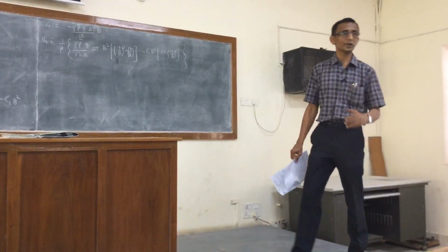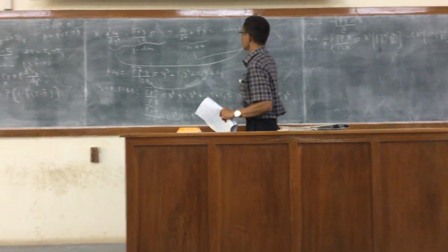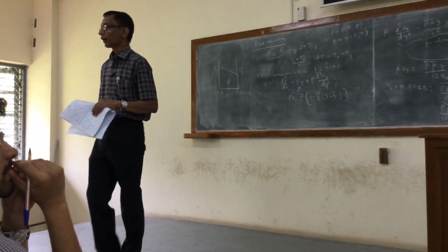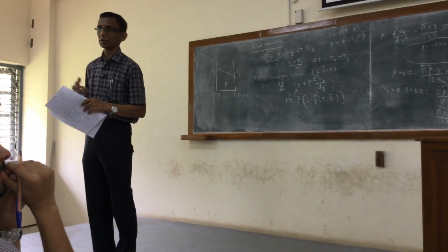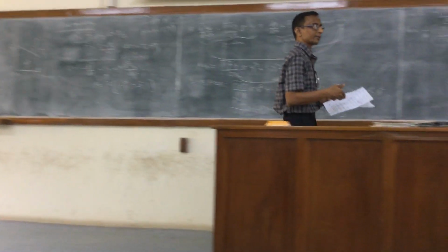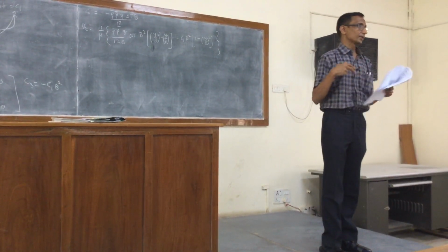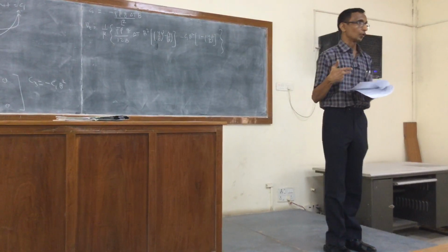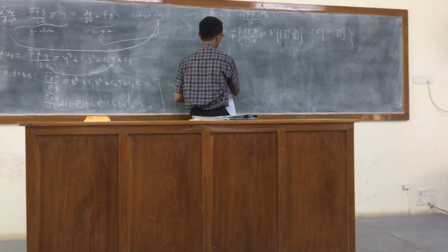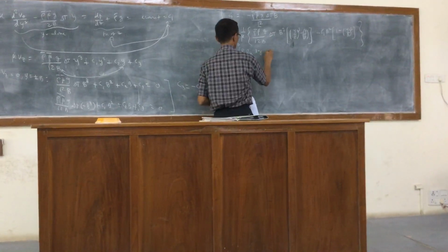And of course C1 has to be determined. If you work out typically, C1 was determined by using this in earlier problems on the incompressible fluid, and C1 is finally expressed in terms of pressure difference, or a modified pressure difference. That's not what is done here. Instead, BSL imposes an extraneous condition that there should be no net mass flow at any cross section. So that translates then to integral minus b to b rho v_z dy equal to 0.